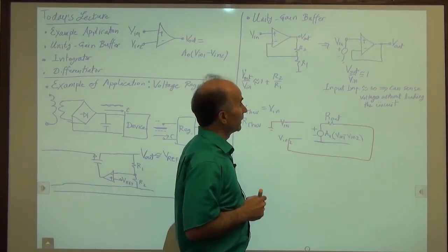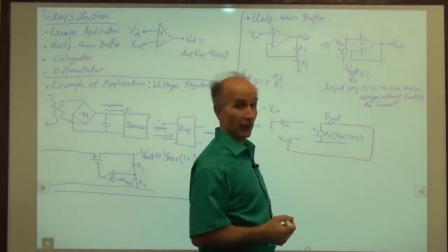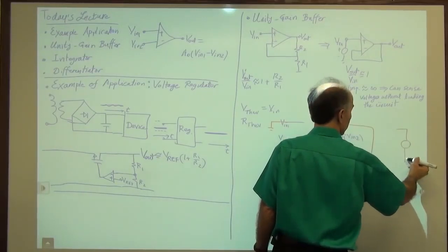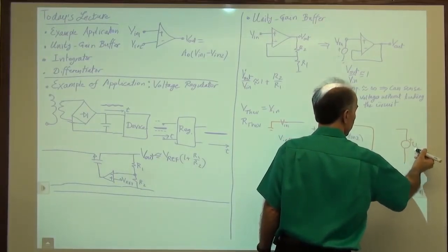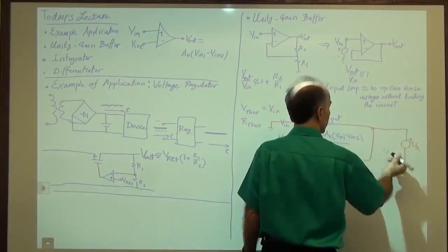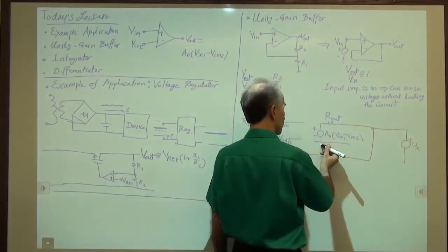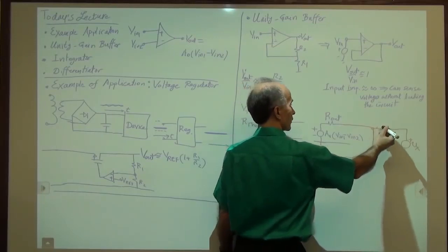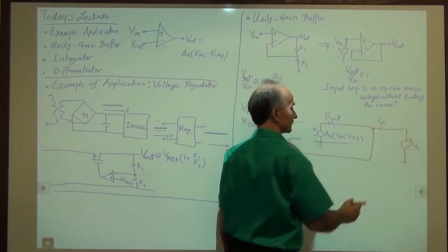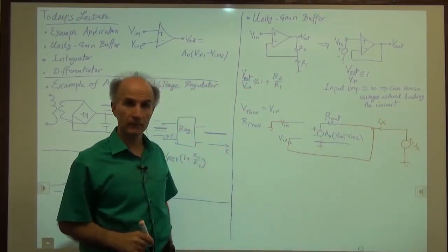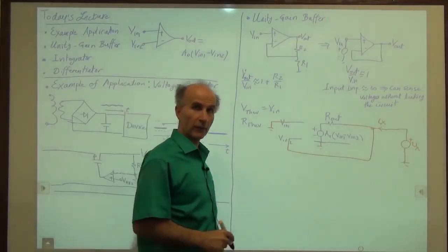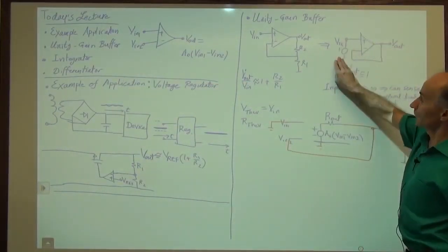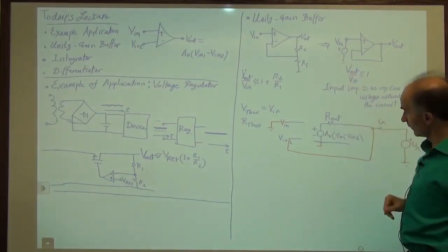And we need to find the Thevenin resistance. So we come from outside, apply a voltage, Vx, to this point, and let's call this ground so that the circuit is not too crowded, and measure this current Ix. This is trying to find the Thevenin equivalent resistance of this whole structure with this input set to 0.